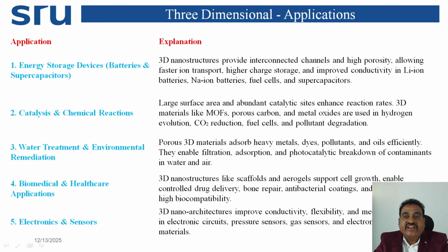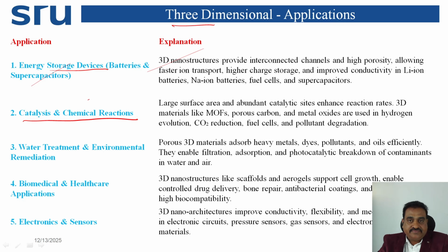So, coming to three-dimensional nanomaterials applications. Yes, three-dimensional nanomaterials are used in energy storage devices, that is, batteries and also supercapacitors. Three-dimensional nanostructures provide interconnected channels and high porosity, allowing faster ion transport and higher charge storage.